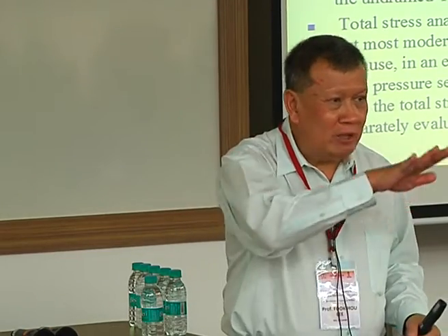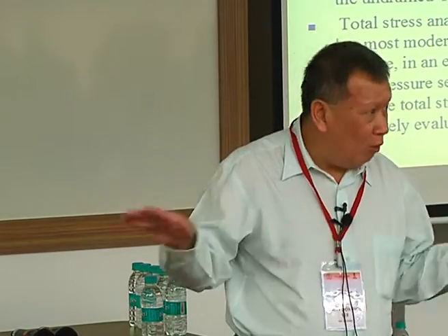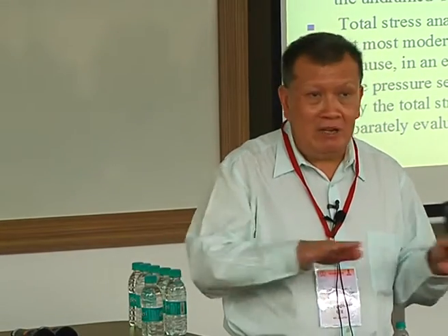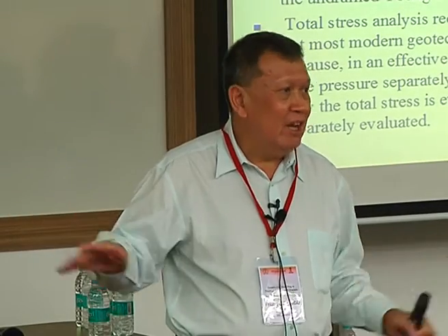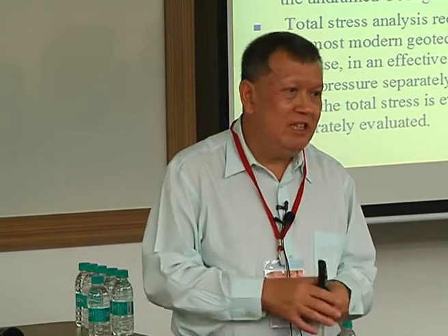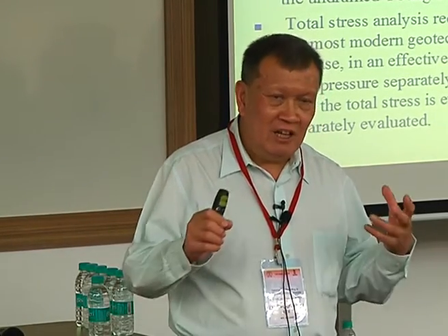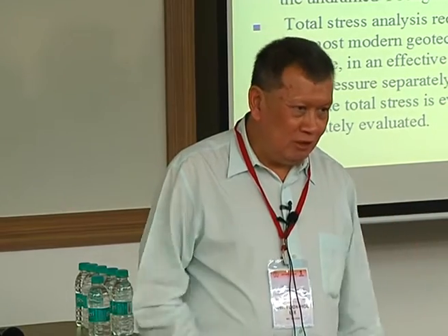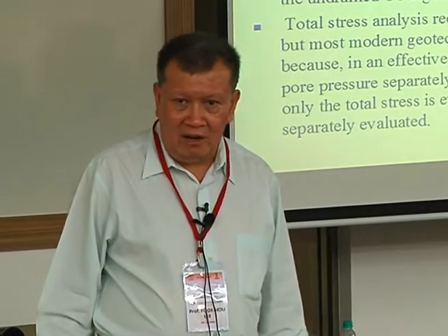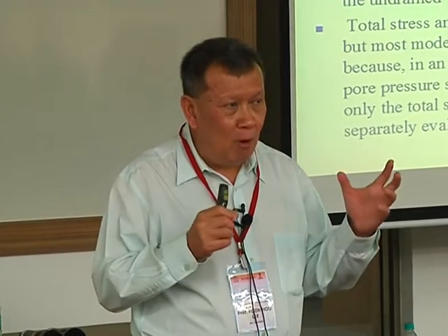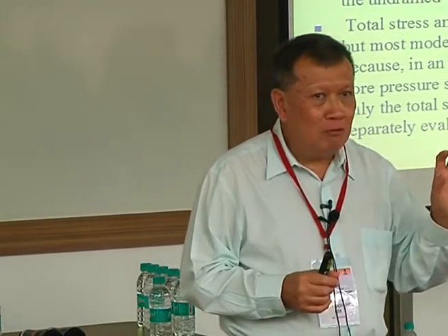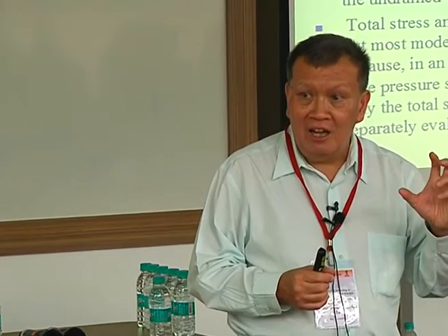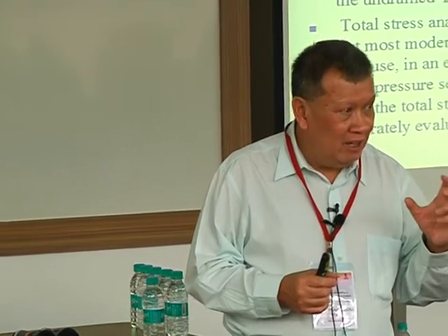Then all the pore water pressure that comes out will look like zero, or there's no change. But in fact, it has no effect at all. That pore pressure has no effect. What it means is that you are not actually seeing the pore water pressure. You are just seeing the effective stress is the total stress. That's all. Is that all right? So you can do either method in most software if you know how to change the parameter in a sensible way.